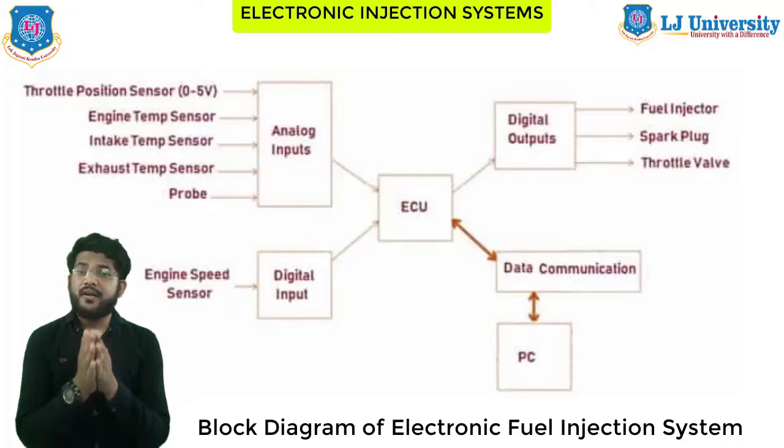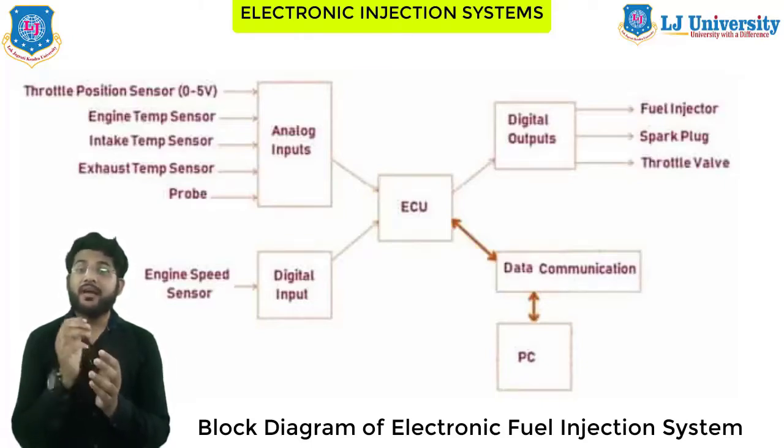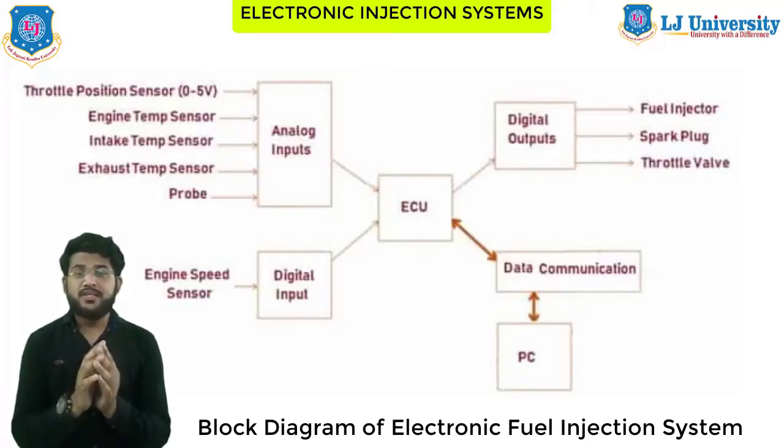Now the sensors continuously detect the values of numerous parameters like air pressure, air temperature, throttle angle, air density, fuel temperature, fuel pressure, thereafter oil pressure, coolant temperature, thereafter exhaust gas temperature, thereafter crankshaft angle, timing, engine RPM, engine speed, etc. Okay, so all this data is processed through the ECU to establish the amount of time for which the fuel injectors are open, injecting the fuel into your engine's intake port. Okay, so these things will create the injection inside the engine.